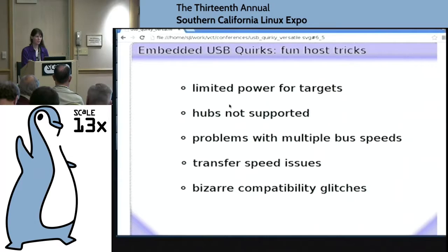the application is such that somebody turns off power on your embedded device by yanking the power cord. That is not actually that uncommon, right? This isn't a real computer. This is embedded. It's an appliance, so people turn off the power any way they feel like it. Nobody expects to have to do a safe shutdown like on a PC. So here you go. You just did that. You turned it off. Your printer is hooked up. You turn the power back on, and you can't get the printer to talk to you again without cycling the printer's power. What the hey?